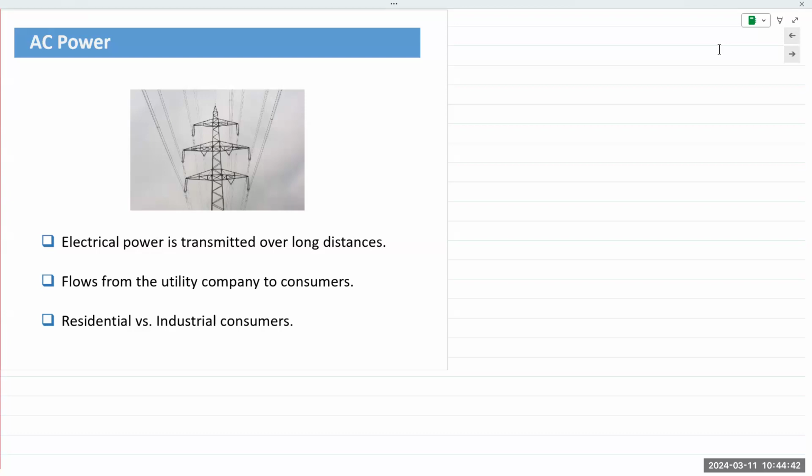That is also one of the reasons why an appliance manufacturer, especially if it draws a heavy electrical load, will tell you not to use an extension cable. Especially in the winters, if you try to plug an electric heater into your wall outlet, they will tell you do not use an extension cord or a power strip. The reason is because consumers would not pay attention to the power rating of that power cord or power strip. So if it draws too much current, that power strip or power cable will get overheated, will short out the wires, and will spark and then do a lot of real damage. That is one of the reasons why that warning is in.